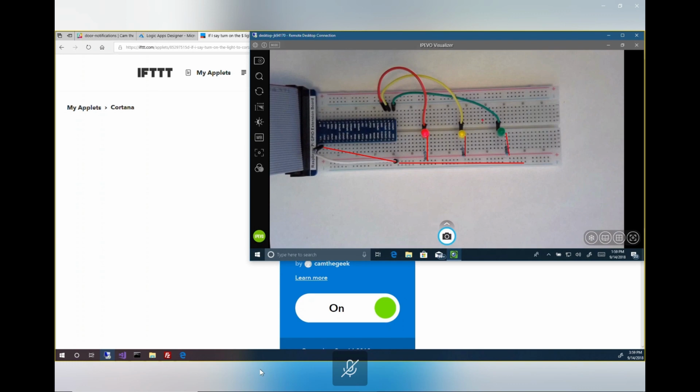And then the cathodes from the LEDs are connected to their respective ports. Since the outputs from the LEDs are connected to the ports, they're going to be blocking the connection when they're high, set to 1, but they're going to be allowing the connection when they're set to 0. So that's why low is going to turn them on and high is going to turn them off.